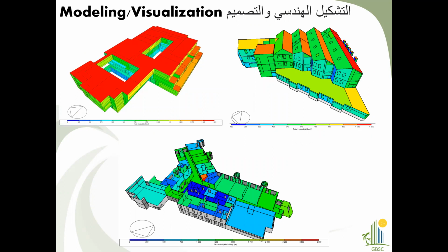Then, if you see within the visualization tool, we can export the outputs as 3D outputs. For the client presentation, instead of showing data in a tabular form, DesignBuilder overlays the output or input information on the 3D geometry itself. So if you want to see what amount of solar radiation is falling onto a surface, or what the thermal comfort of different zones is, we can extrapolate that within the 3D module, and the information which is output in tabular form gets reimposed within the 3D output form.